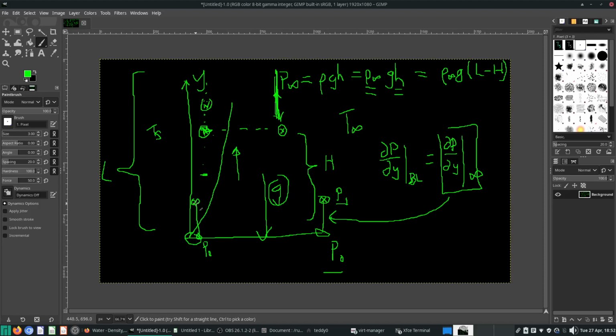If you move up a little bit into the boundary layer, where the convection started, let's call this pressure P2. By intuitive reasoning, the fluid here is hotter, therefore the density of the fluid above is less. What do we expect? We expect the hydrostatic pressure to be less, so P1 should be greater than P2 if P0 is the same.